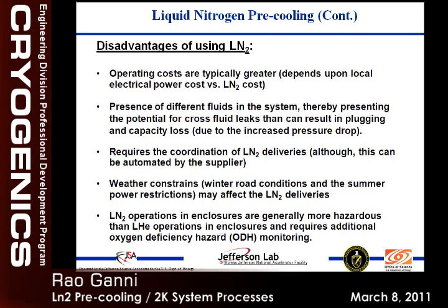So what are the disadvantages then? Why don't we just use it as a standard practice? Operating typically costs you more, because you have to truck it in, you have to maintain it. Now, there is the presence of different fluids. If the nitrogen leaks in, it can contaminate the helium, and it requires coordination every day. Somebody has to sign for these trucks, take the delivery. You have that nuisance factor you need to put up with. You have weather. Of course, it doesn't bother us as much as it used to bother, say, Fermilab, and then they built their own nitrogen liquefier on site because of the weather dependency.